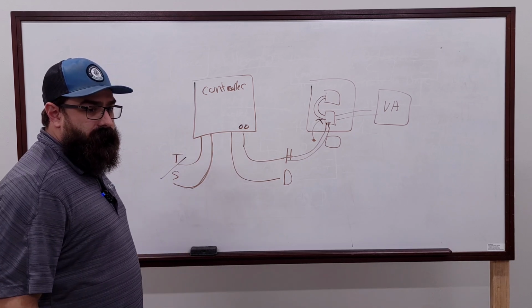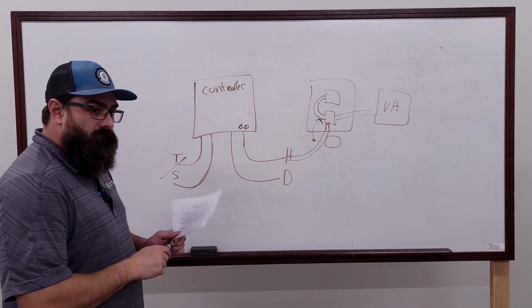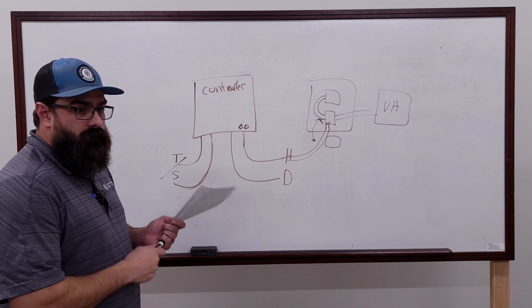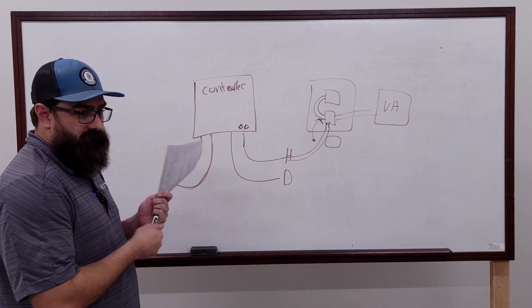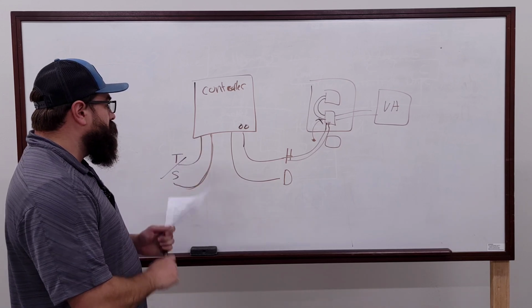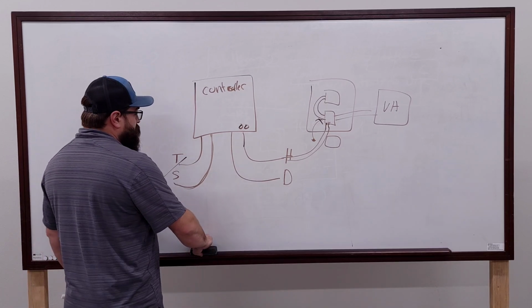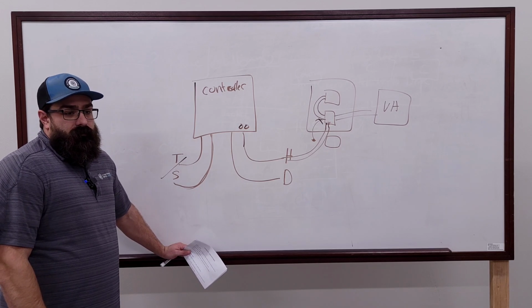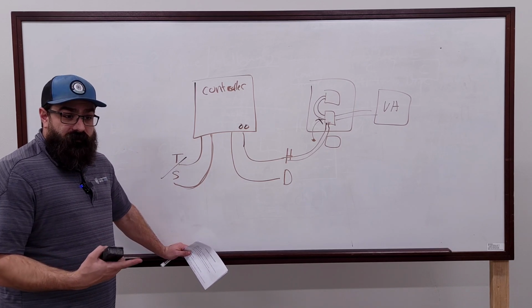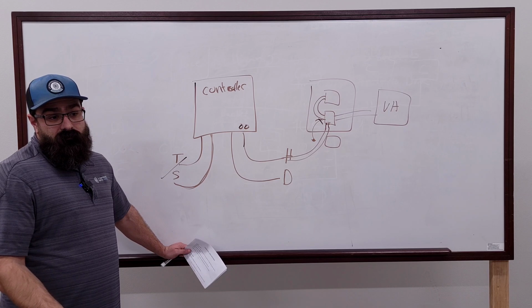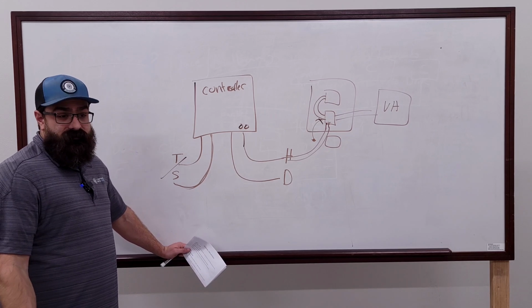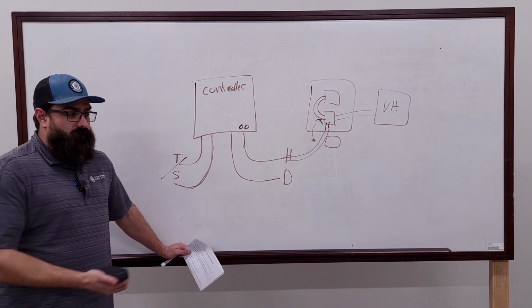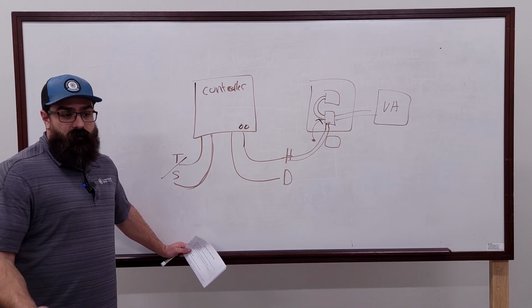Yeah, I wasn't getting anything out of the controller, but when I put 9 volts DC to the SCR signal, yep, it came on. Okay. So at that point, the only thing you can do, you would need to go in that controller, make sure you have the right output, first off, because they may have miswired it, right? I mean, that's happened hundreds of times. Even with us, that's why we always double check our work.